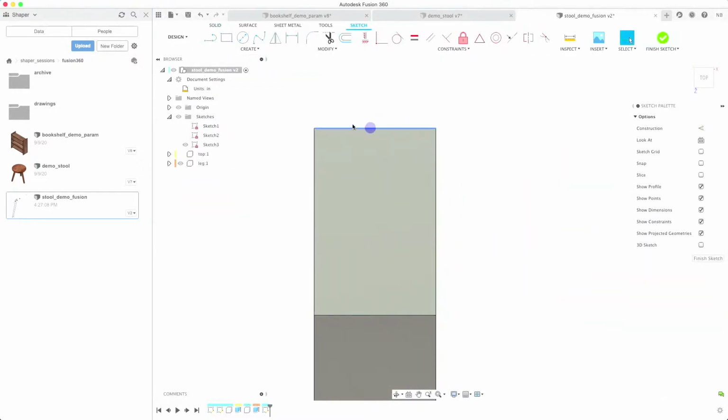So quickly here, I'm going to do two things. I'm going to create a rectangle that's the profile, and I'll show you why I'm doing that in our export for origin section here. And now I'm going to create the geometry for our tenon. So I'm going to get the line tool. And this is kind of a neat one here. I'm going to click once to start dragging a line upwards. And now, instead of just clicking again, I'm going to click and drag, and you'll notice that Fusion automatically makes an arc, which is pretty cool. So now I'm going to let go of my mouse button, drag again, click and drag again. Fusion's making that arc. And on round we go.